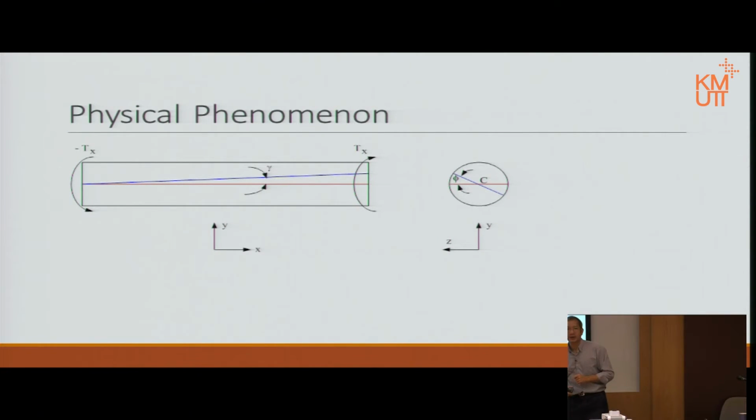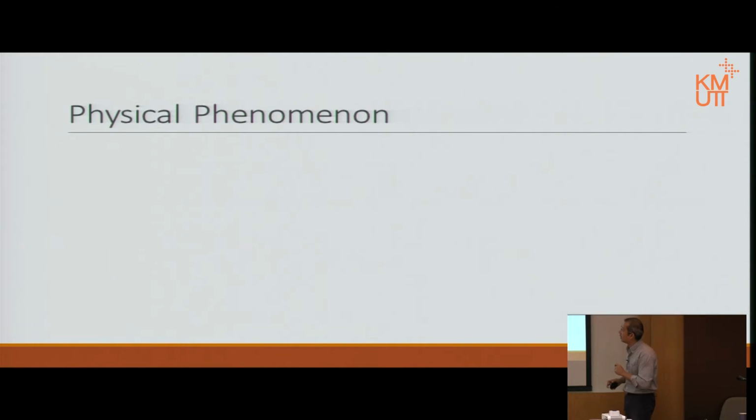Now, notice one thing though, on one cross section, the angle of twist phi is constant. Not gamma, sorry. Look at that, no matter where you measure, from that point or that point, it is still the same phi, the same angle of twist. Gamma also seems to be constant throughout the whole length, at least in this case, if there is only one torsion.